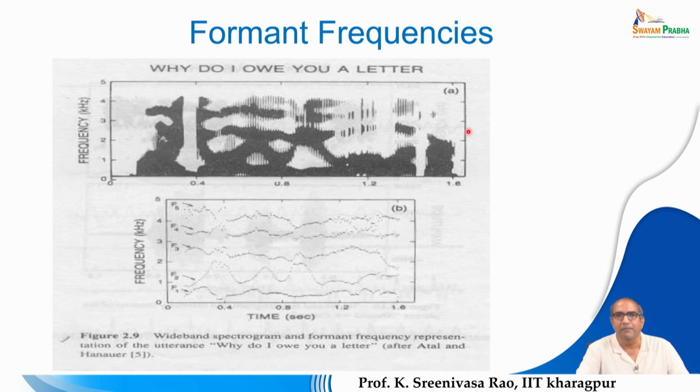This is your spectrogram, and the bottom figure is known as the formant plot. I'm introducing a new term here. As I mentioned, in the spectrogram you observe three, four, or five frequency ranges where most of the energy is concentrated. Since we sampled the speech signal at 10 kilohertz, the frequencies present go up to 5 kilohertz.